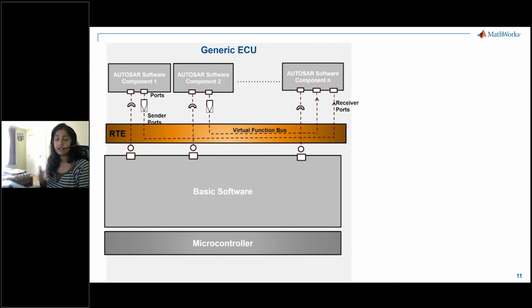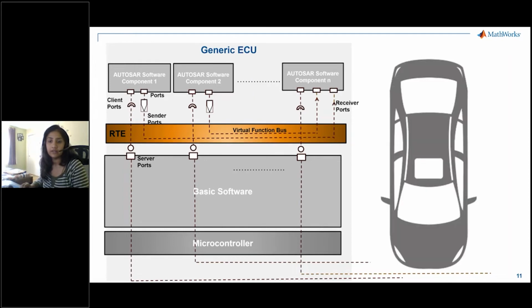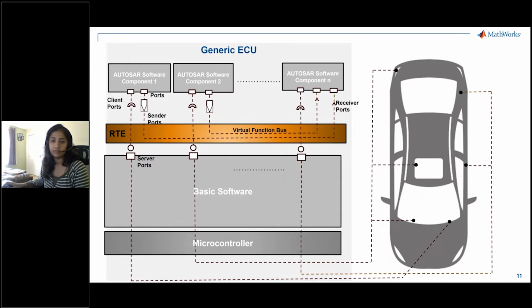For example, my client AUTOSAR software component is calculating the average vehicle speed. When the overspeed occurs, then the server diagnostics software will set the diagnostics error. Then the application output is plugged to the hardware pin, which will control the actual application on the car, related probably to body control module, powertrain, safety, and so forth. Now I have a real example, which is an exterior lighting ECU.